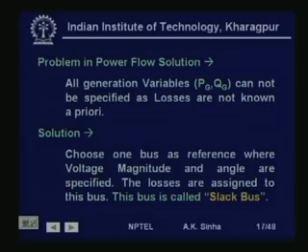So, for this bus, which we consider as the reference, the voltage magnitude and phasor angle are specified, and the real and reactive power are allowed to vary at this bus. All the other buses take their specified generations. So, whatever losses are coming, plus the deficiency in the generation, are all assigned to this bus, and therefore, this bus is called a slack bus bar or a slack bus.